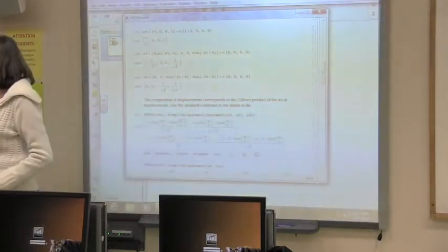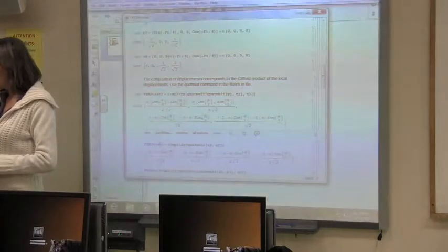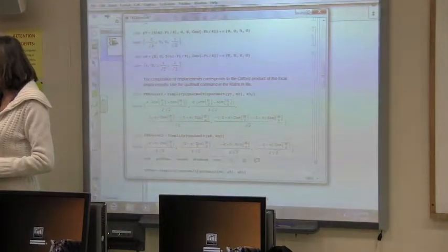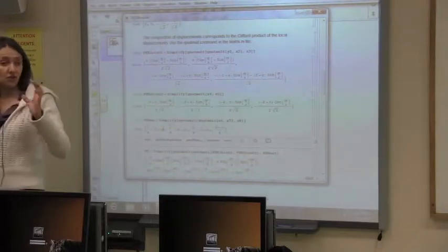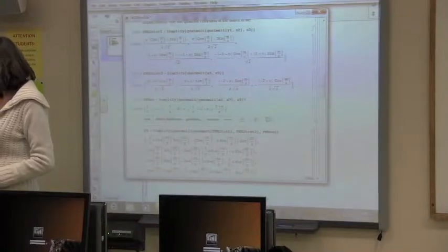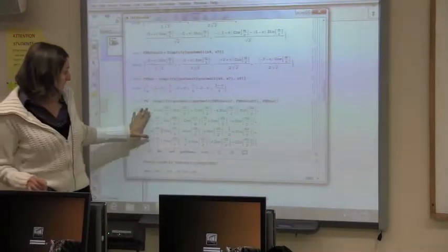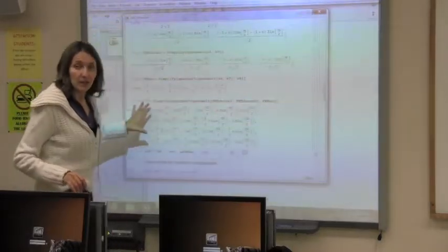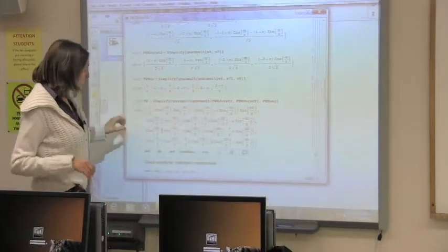Okay, so that's up to from the origin, from the base to the first joint rotation, and from the first joint rotation to the second joint rotation, then from the second joint to the end effector. You can associate them however you want, and then I just multiply everything together, and this is what I get. So these over here are the forward kinematics equations of the robot in dual quaternion form. Okay.